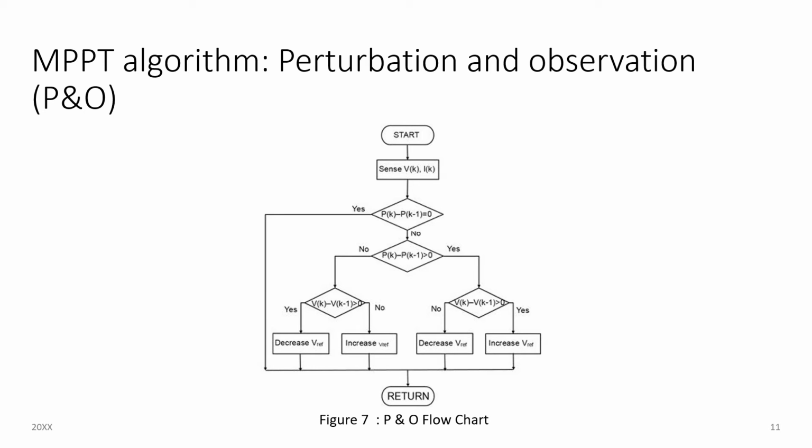Maximum power point tracking is an algorithm implemented in photovoltaic inverters to continuously adjust the impedance seen by the solar array to keep the PV system operating at or close to the peak power point of the PV panel under varying conditions like changing solar irradiance, temperature, and load.